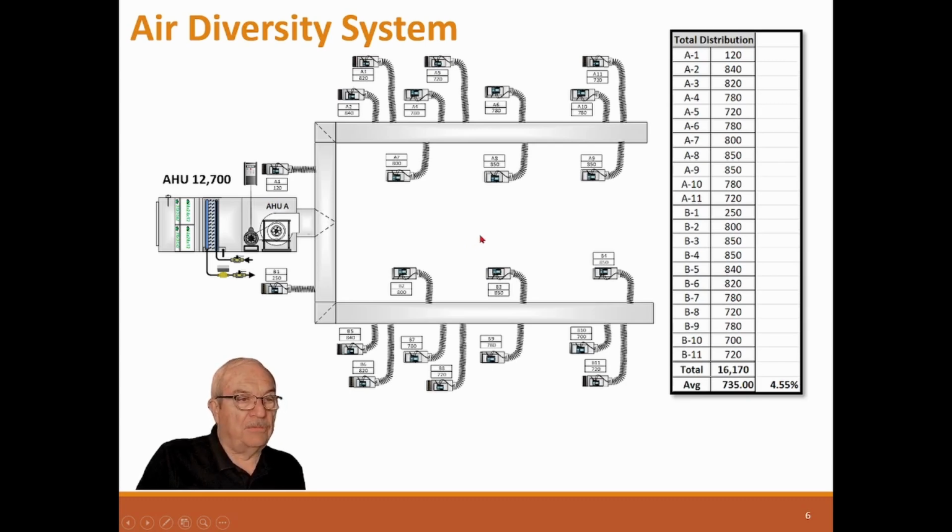It's similar, but it's slightly different. And the session on VAV balancing will cover that. But this is strictly for systems with diversity. So we have 16,170 CFM, and the diversity is 78.54%. And the shortfall is 3,470 CFM, or 21%. So you can see we're in that 20 to 25% exterior load.